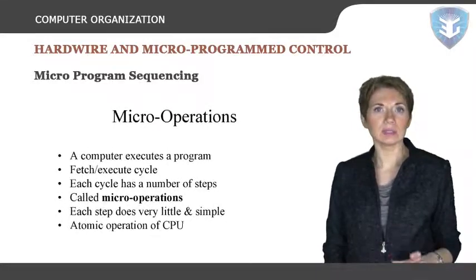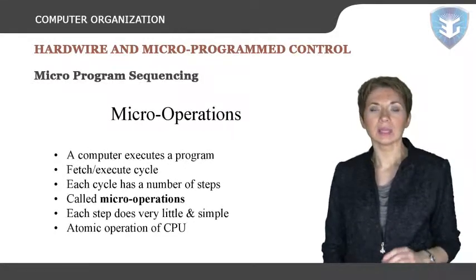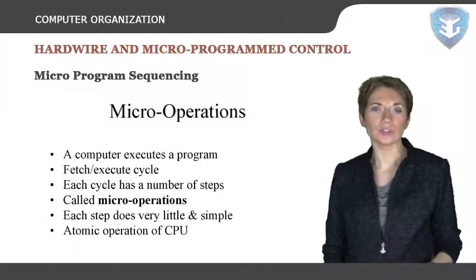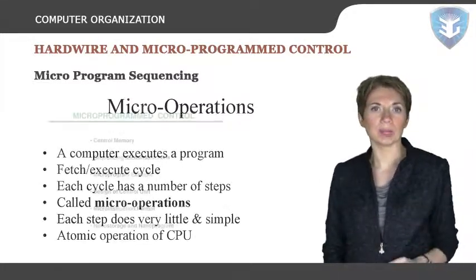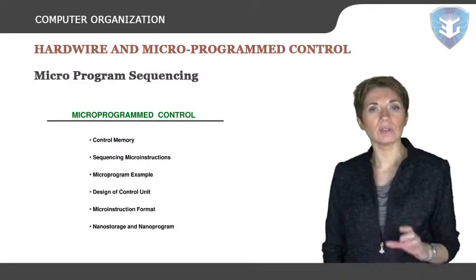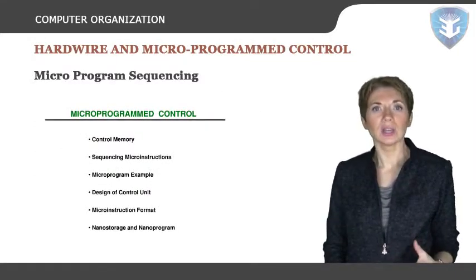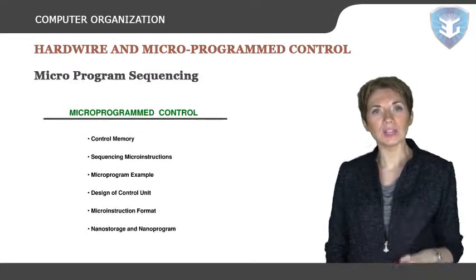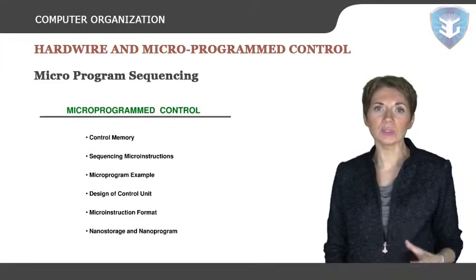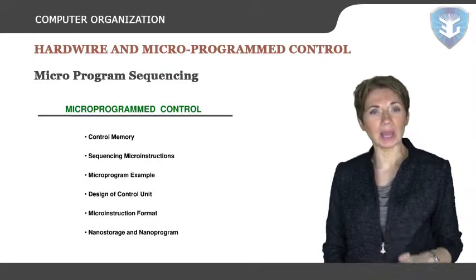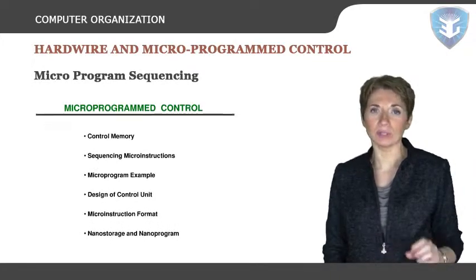If cleared, the signal will be inactive. Sequences of microinstructions could be stored in an internal control memory. Execution of a machine language instruction could then be caused by fetching the proper sequence of microinstructions from the control memory and sending them out to the data path section of the computer.